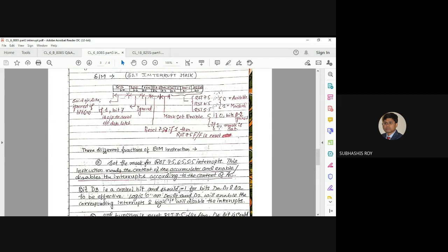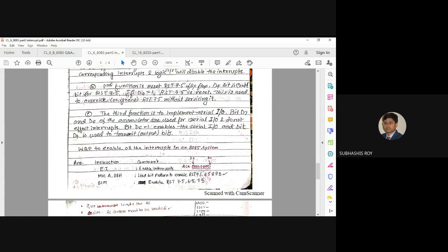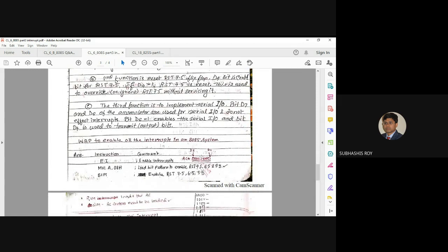If you put 0 there, these three bits will not be considered. So D3 is 1 and the rest are 0, so it becomes 8. The other bits are not useful, so you put all 0000. So your data becomes 08.